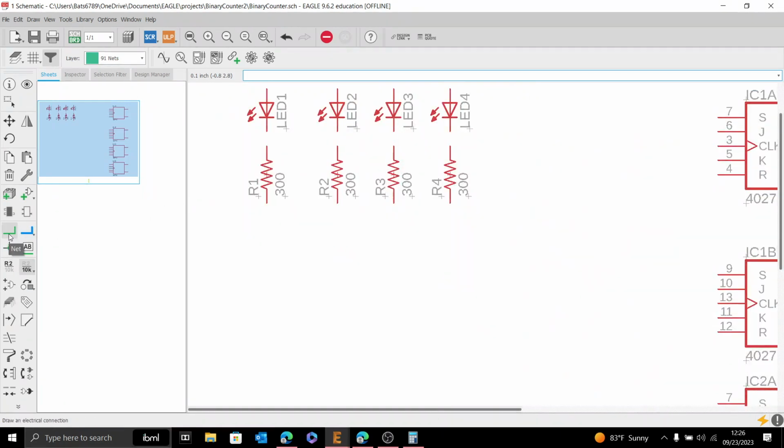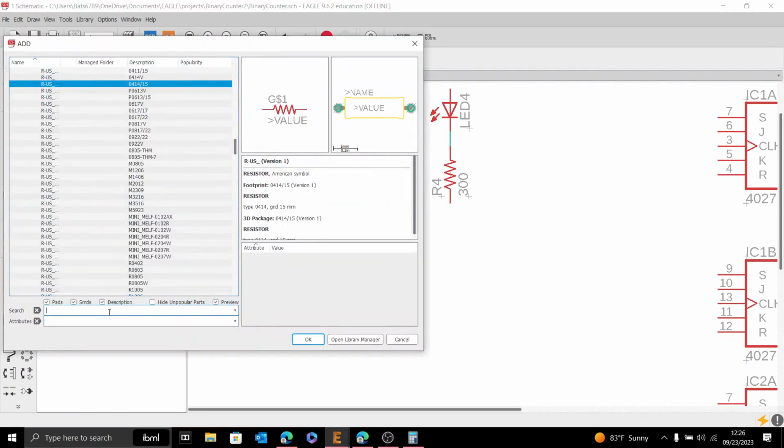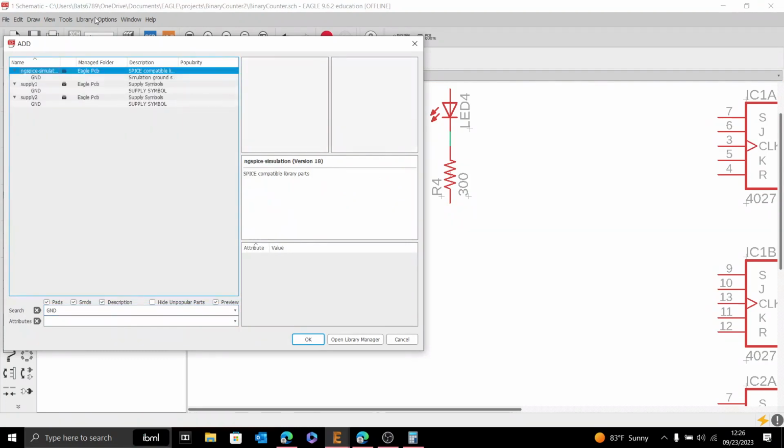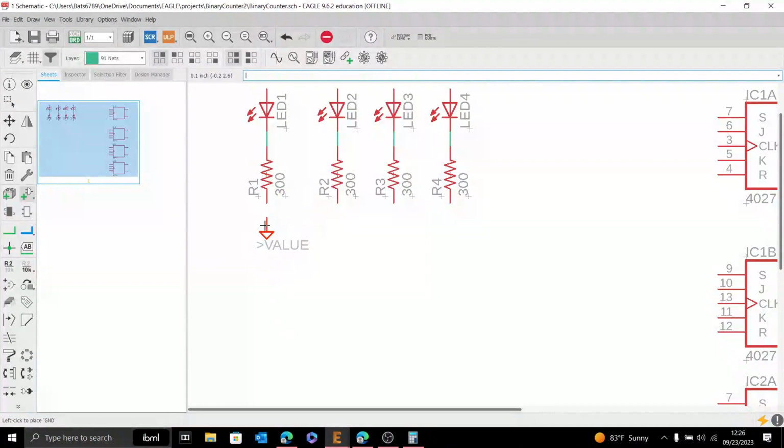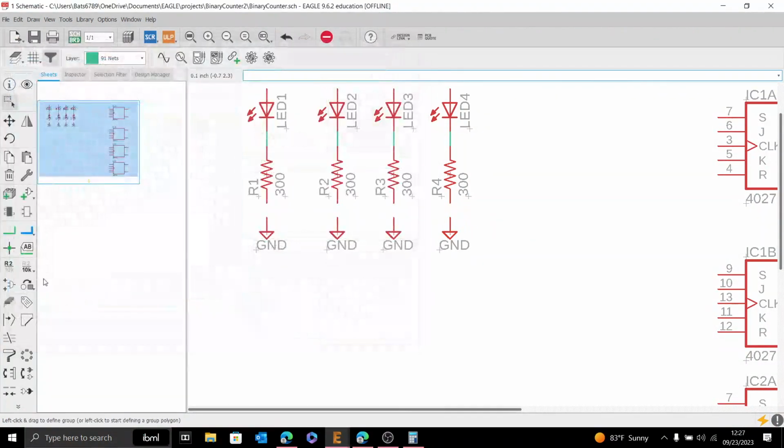So we have this little button here named Net, and these will let us add our little wires to these LEDs. Let's also take the time to add a ground, and I believe the grounds are just here. We'll go with, I like this one. Boom, boom, boom, and boom. And then we will, not the bus, the net. There we go. Wire these up.